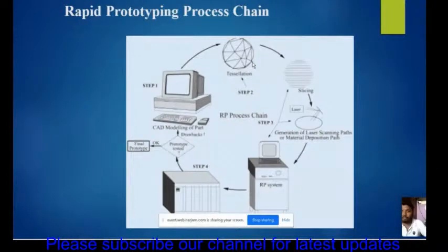0.01. If you are not giving that, then in the output of your 3D print you would be getting a spot of a big triangle like this. So if you are giving the right tolerance of 0.01, your model will be perfect, and the finished model will look flawless, and any line or anything will have a smooth finish.